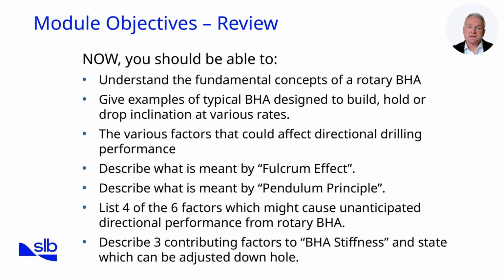The key message is that rotary BHAs are not static systems. They respond dynamically to drilling parameters, hole condition, and formation forces. By integrating design knowledge with operational awareness, you can predict behavior more accurately, reduce unplanned deviation, and optimize drilling efficiency.